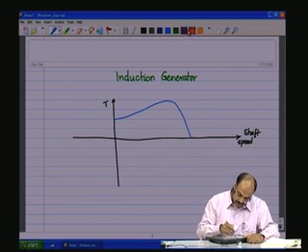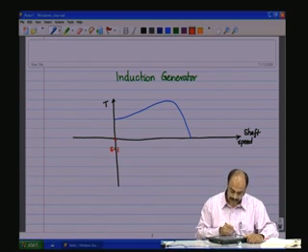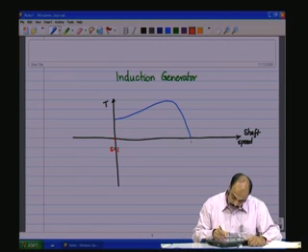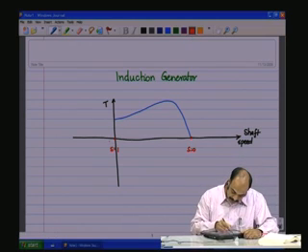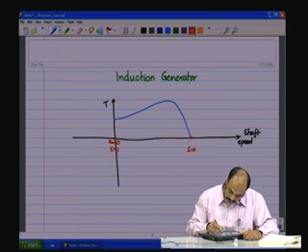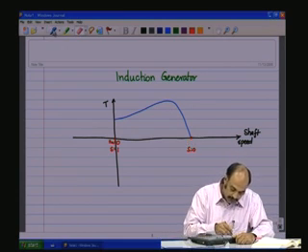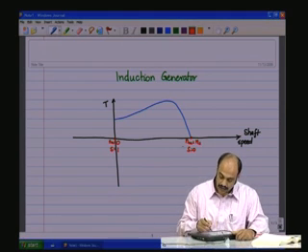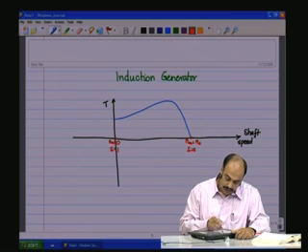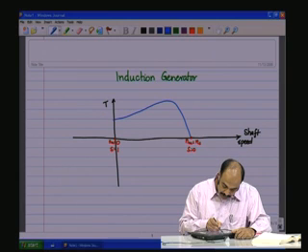is the torque that we see from S equals 1, this is stationary, standstill, to this point S equal to 0, which means speed wise Nm is equal to Ns at this point, the synchronous speed. So beyond that is the super synchronous speed, and below this one is the negative speed. In the negative speed we also saw in one of the examples that there is braking.